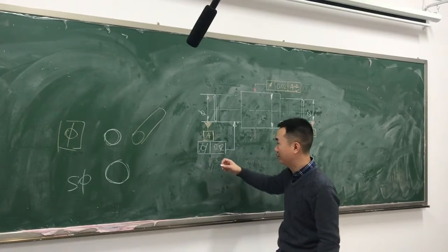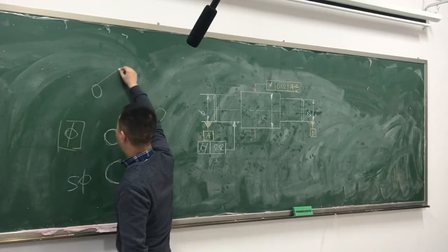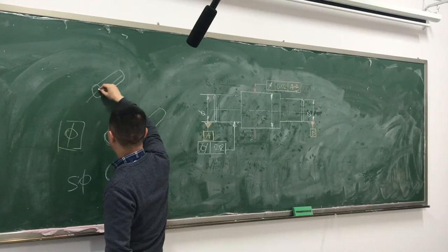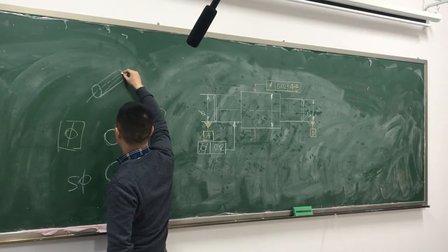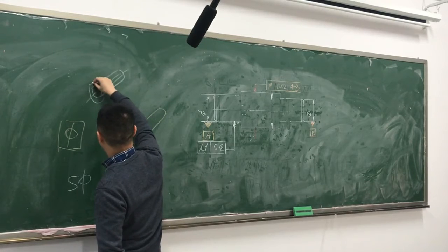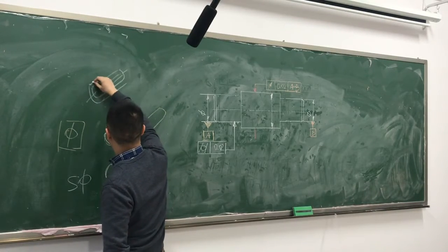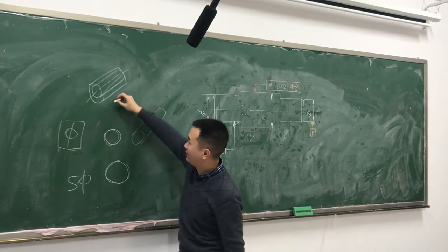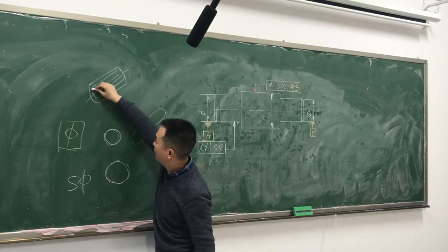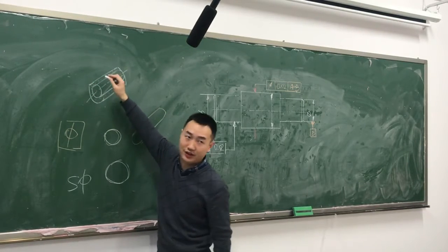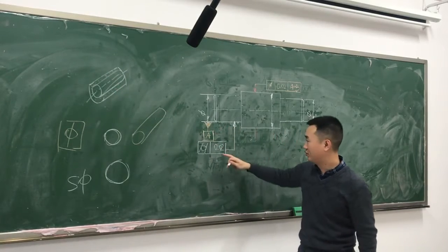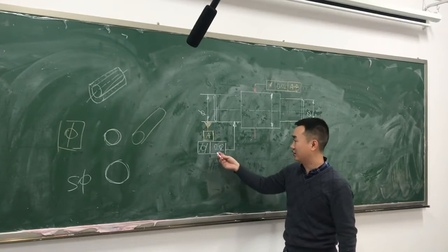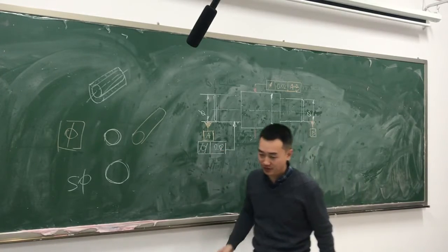In fact, the tolerance zone is the space between two coaxial cylinders. So the tolerance zone is not a cylinder, and we should not add a phi before it.